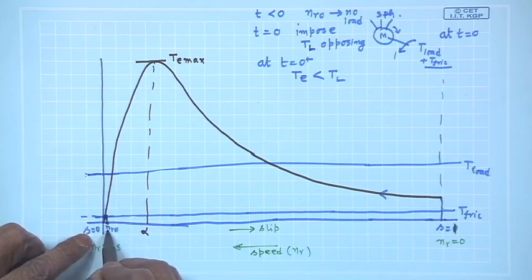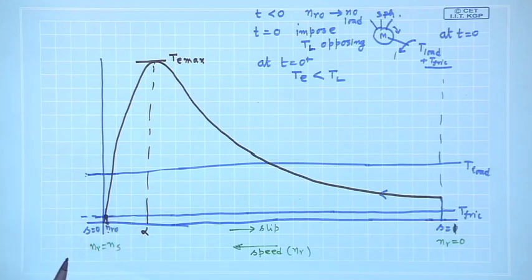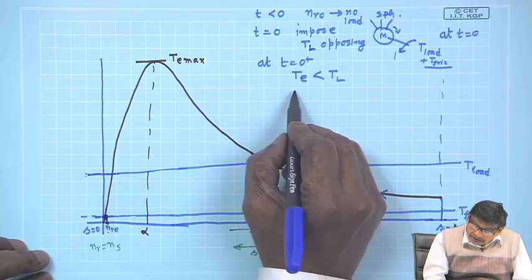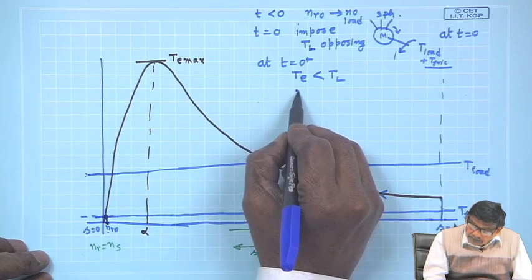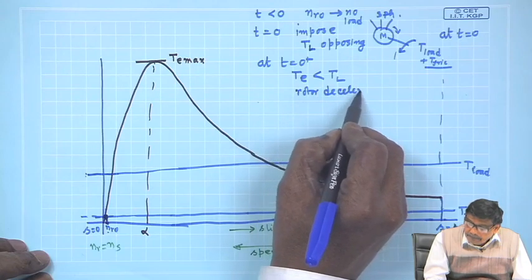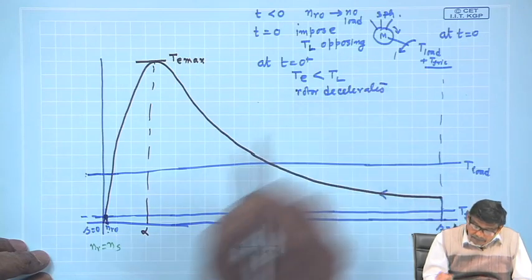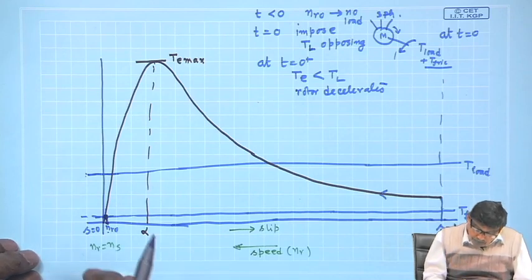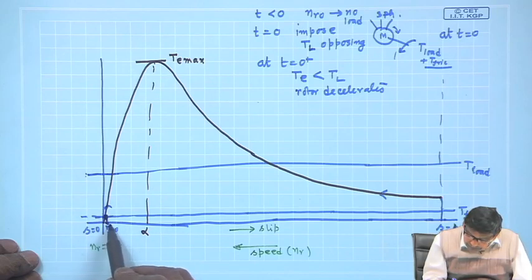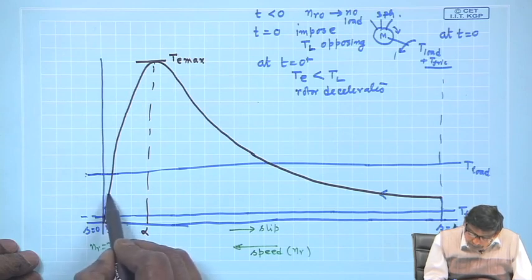and the electromagnetic torque is only this much. Therefore, what is the motor going to do? The motor will decelerate, the rotor decelerates. Now, the rotor decelerates means speed decreases, therefore the operating point starts moving; speed will now decrease, this way it will move.